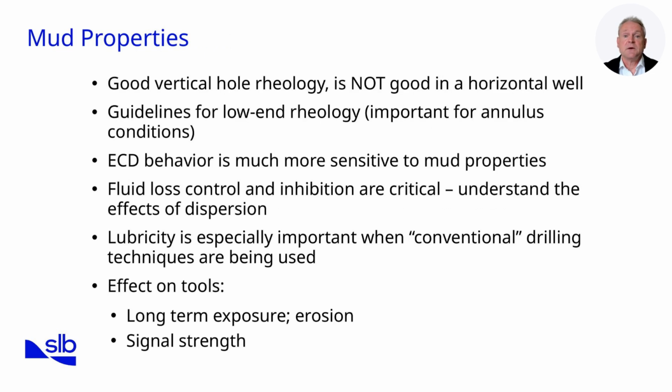When it comes to mud properties in extended reach drilling, it's important to note that what works in a vertical well does not necessarily work in a horizontal section. Rheology that looks perfectly acceptable in vertical drilling may lead to inadequate hole cleaning in long horizontals. This is why we follow guidelines for low-end rheology, to ensure that annular cuttings remain suspended, particularly at low flow velocities.